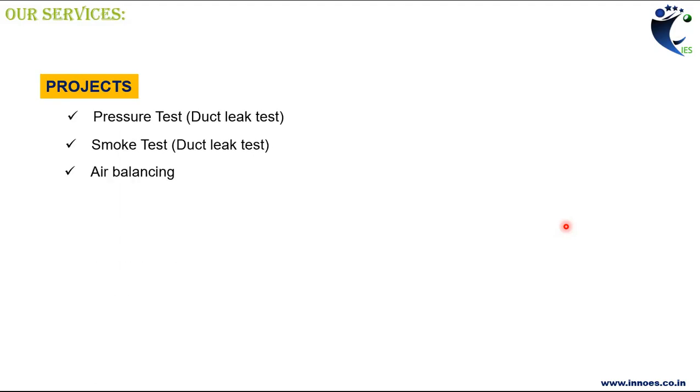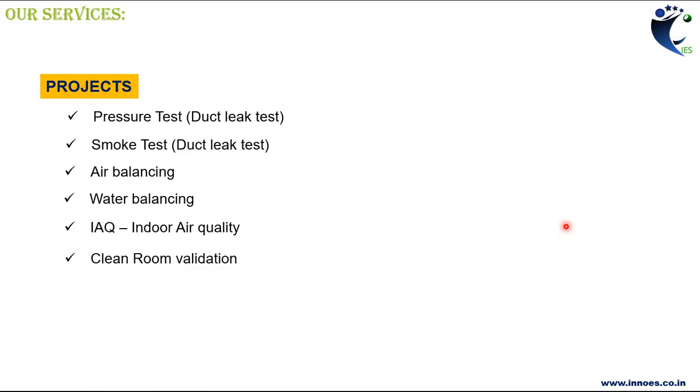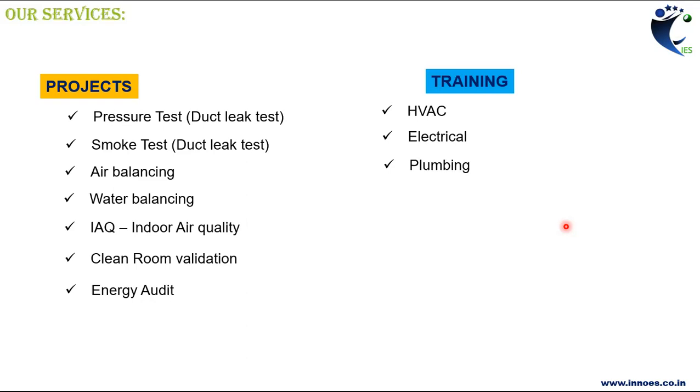Generally in the chilled water system, the water quality is going to be checked. That means the pH level. Last class itself I told you about the sea source area, water demand area. Generally, you go to select the air cooled chiller. Why? Because in the sea source area, the water quality is poor. You know that water is salty. So for the water cooled condenser, that is a shell and tube condenser.